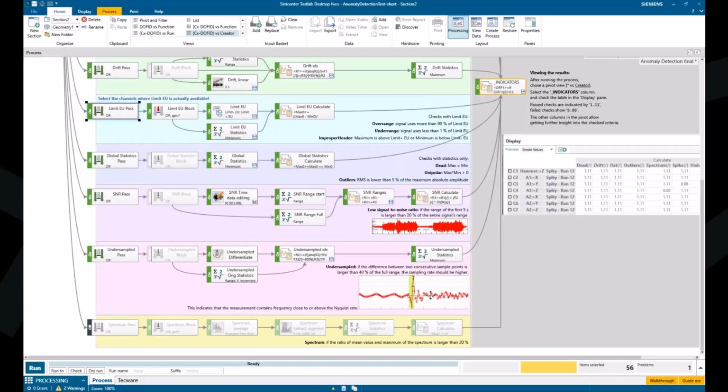And the signal continues here also with not so nice sine waves, but still this is considered okay. It's smaller amplitudes, the changes between samples are okay. So we will not flag that as a problem, but these large changes compared to the full range of the signal, this is something at least you can look at.